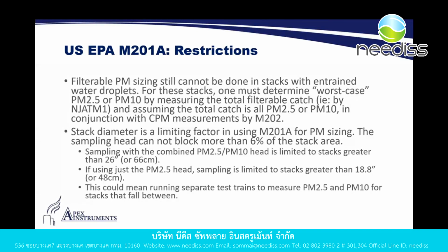As much as we would love to be able to do this method on any stack anywhere in the world, if a customer would like us to do it, we do have to consider the limitations of the method due to certain parameters of the stack, of the gas, for moisture, etc. So the first and most important point here is that filterable PM, whether it be Method 5 or this Method 201A, you still cannot really do this method in stacks with what is called entrained water droplets.